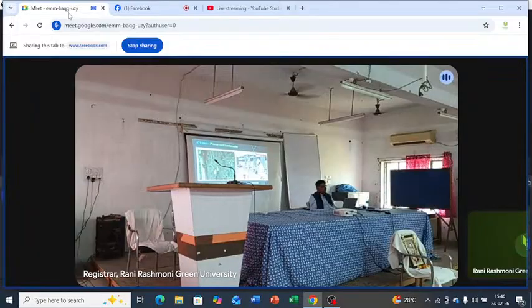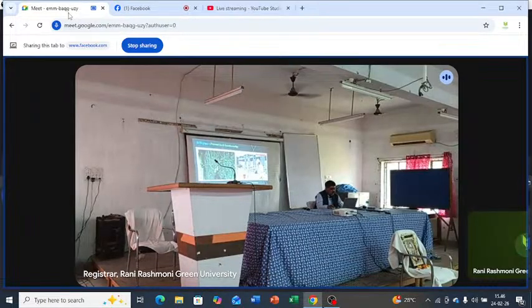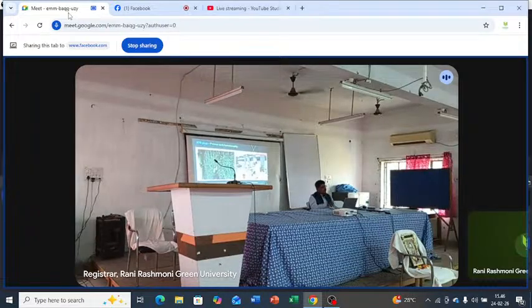Now for this you must have two important features. One is the lock feature. See, there are two prisms, one behind the tree. The prism that I want, or locked in, is the one which is moving, and there is a large prism in front of the tree. But in spite of that, it is not shifting to the other prism that was locked. And there is a dynamic lock facility, which is to lock to a prism which is even moving, and it will just lock to it.